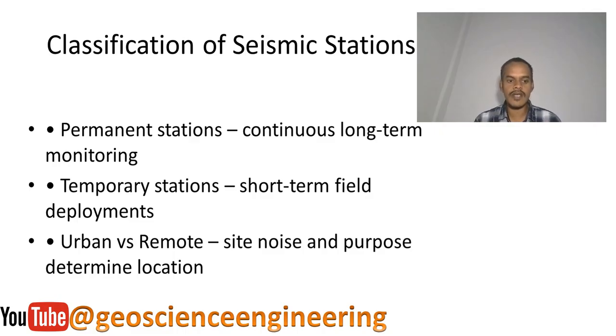And then when it comes to communication, some people use satellite communication like VSAT, and some go for cellular or microwave radio links. You can even use routers with a SIM card, so the SIM card will provide you the internet, and the instrument will take the data and send it to the server through this internet. And also we need to make sure that this equipment is not exposed to harsh nature, so we have to do some protective covering, and this also I will show you.